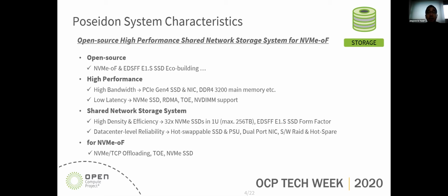It is a PCIe Gen 4 based system and supports DDR4 3200 main memory. The reference system has up to 32 E1.S SSDs and supports up to 256 terabytes of storage capacity in one server. And the new form factor EDSFF enables a highly dense and highly efficient system design.